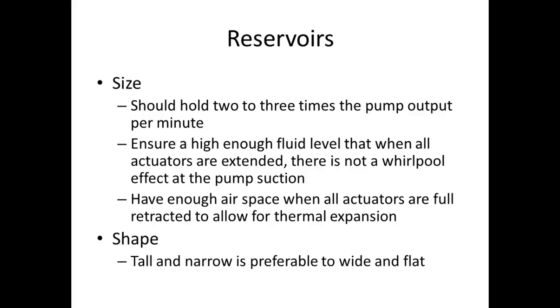And what's that doing? That's sucking air into the system. So you want to make sure that when that pump is pulling from the bottom, and all your actuators are fully extended, there's still enough fluid in there to keep the pump from creating a whirlpool, because that would put a lot of air in, which is not good.